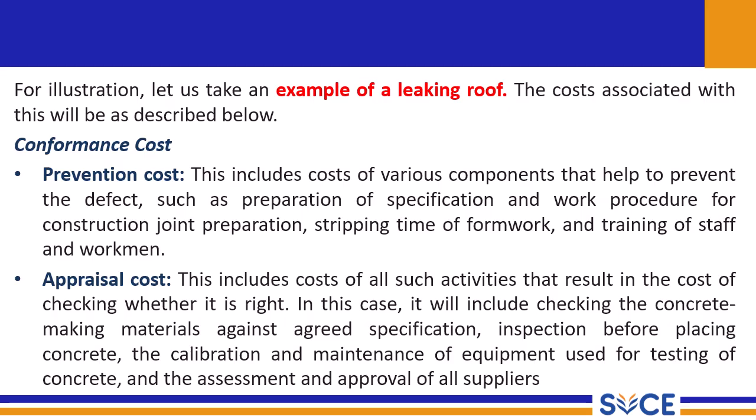Appraisal means the cost of all activities that check whether it is right. In this case, it will include checking the concrete making materials against agreed specifications, inspection before placing concrete, calibration and maintenance of equipment used for testing the concrete, and assessment and approval of all supplies. So we spend money on inspection, and some money on maintenance of equipment. Those are the things that come under appraisal cost.